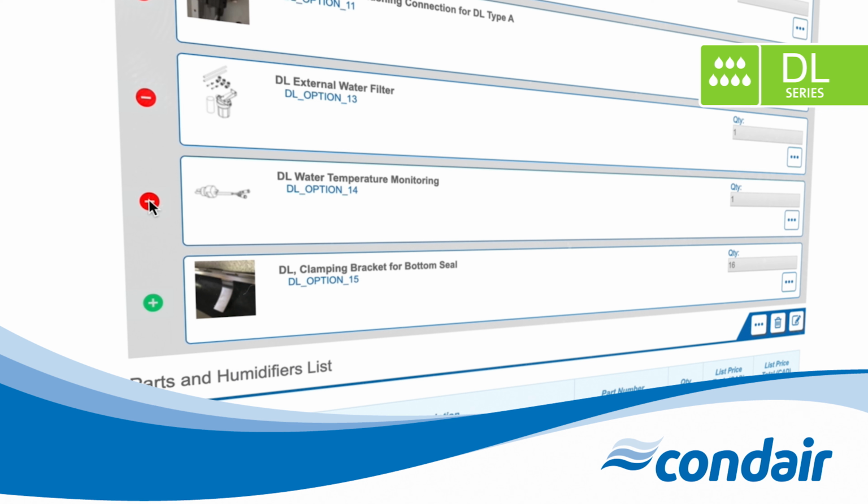The water temperature monitoring option protects the system from freezing and prevents microbial growth by triggering a 2-stage temperature flush of the entire water circuit if the water temperature is either too high or too low. This option is good for both outdoor applications and for Legionella risk management as per ASHRAE 188.